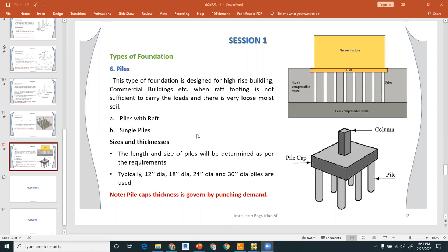I will further clarify. Wall, I mean the masonry walls. Normally, shear walls are also part of the design. So, about the masonry wall, can we model them in the software? You can model the confined brick masonry in ETABS, but there is no unconfined brick masonry model in ETABS. Yes, ETABS can model the confined brick masonry for you.